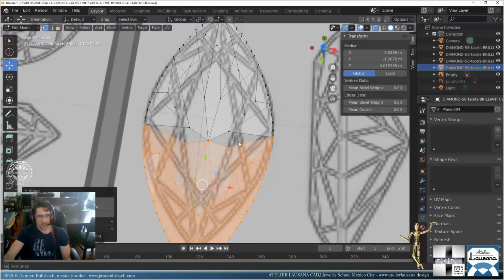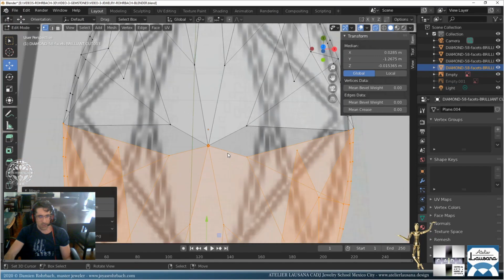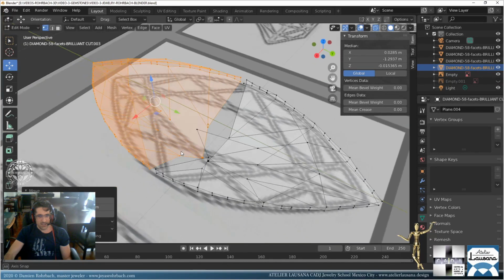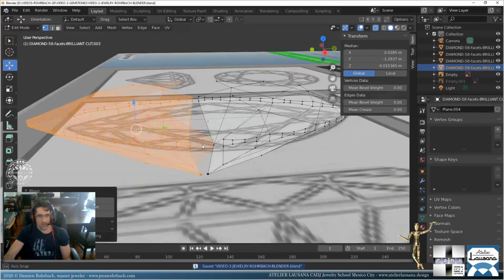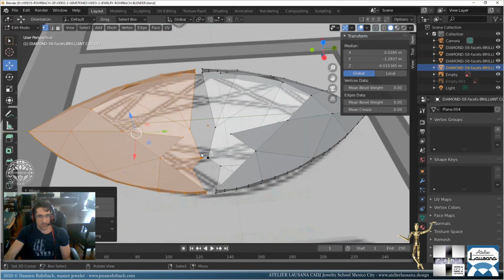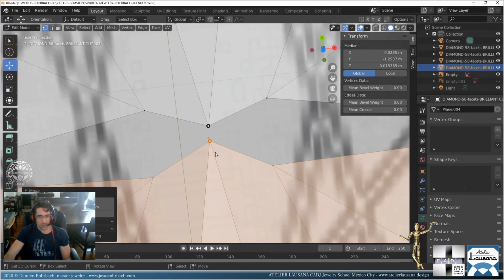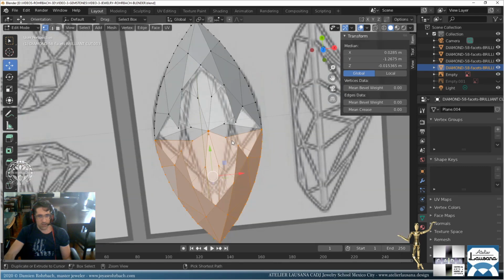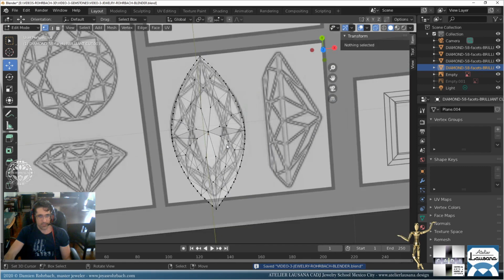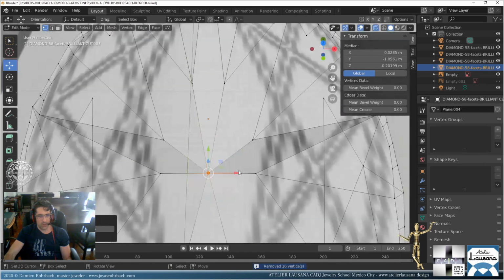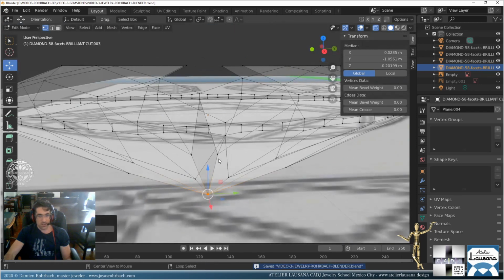And now we can start completing, but we obviously are going to have a small problem of connecting that to that. To avoid the overlap, because the overlap might create a lot of problems, and obviously we can't make a good mesh with these overlappings, I need to remove. Yeah, it's better if I remove. Or we can try, let's try with the overlap, but okay, let's select this and let's do a merge by distance. Okay, 16 removed. But I don't know if that's going to make the correct connections. I think it does though.